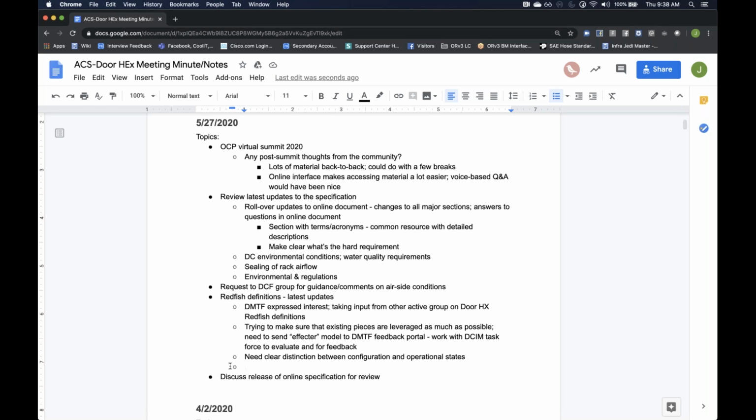Yep. Now, another thing on operational versus configuration is rear door coolers and in-row coolers. Generally, the controller inside of them has lots of different mechanisms for managing the water flow and the airflow. You can do it by water temperature differential, air differential temperature, or air pressure, and usually the controllers inside are capable of lots of these.